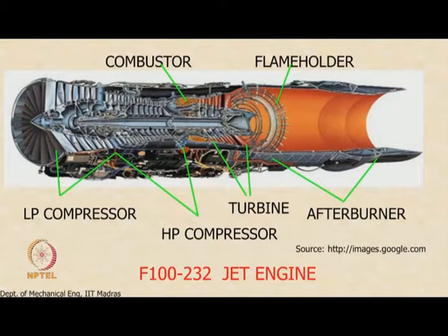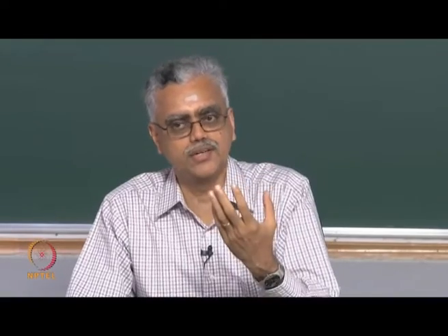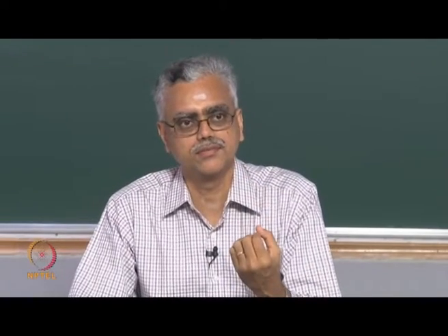Here you can see the cutaway view of the engine. You see the discs, the blades, and the discs here. You can also see that all these regions, as I said earlier, are hollow. So, you take cool air from the front of the engine and send that cool air in a controlled manner into these hollow regions. The cool air tends to shrink the disc. So, when the disc is trying to expand due to elevated temperature, you try to shrink the disc.